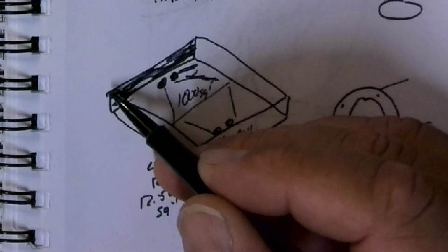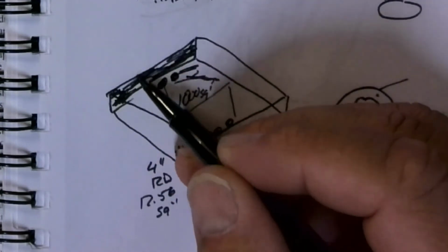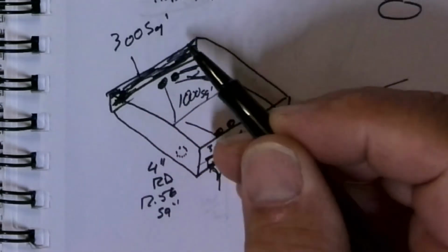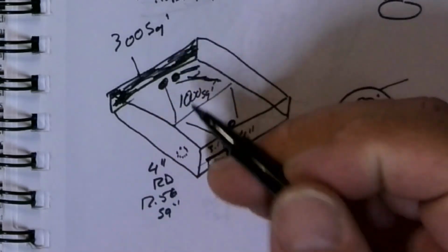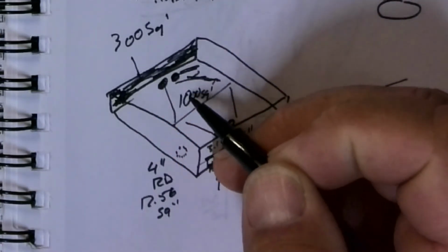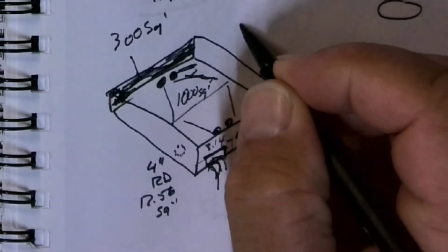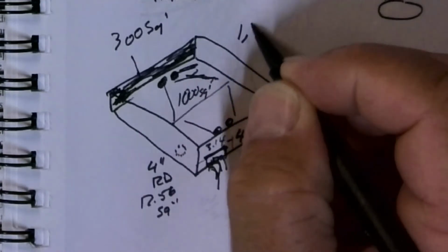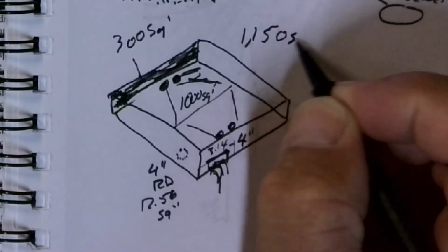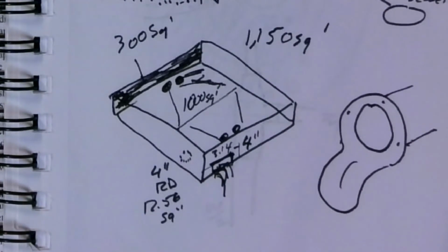It's small. 100 by 3 is 300 square feet, right? So this little sidewall is 300 square feet. I have to take 50% of that, which means it's going to be 150 square feet. And I'm going to add it to this 1,000 square feet for this one. So these roof drains are actually receiving 1,150 square feet. Okay, that's what they're talking about.